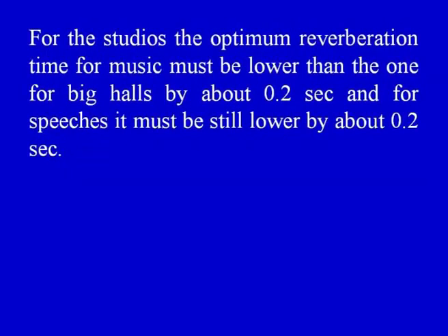For the studio, the optimum reverberation time for music must be lower than the one for big halls by about 0.2 seconds, and for speeches it must be still lower by another 0.2 seconds.